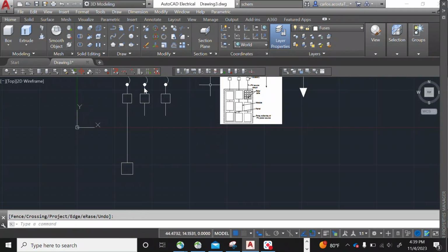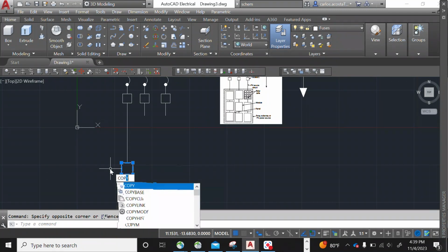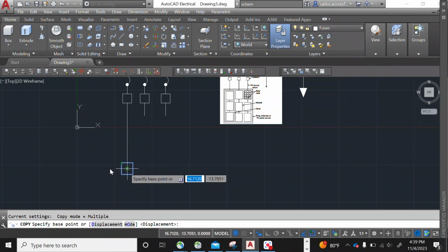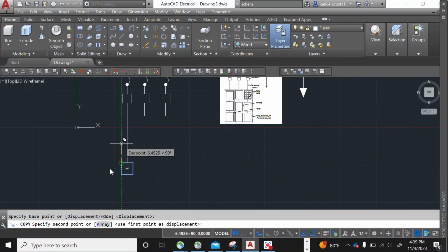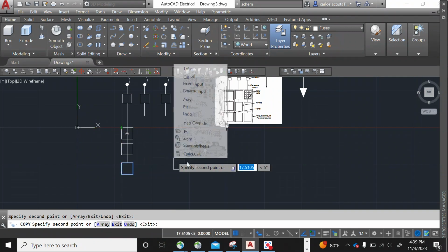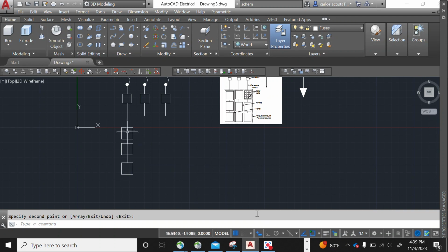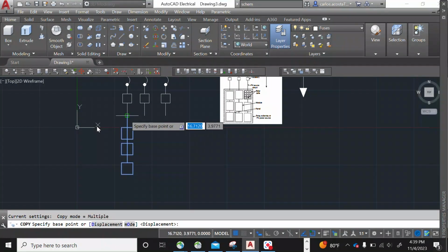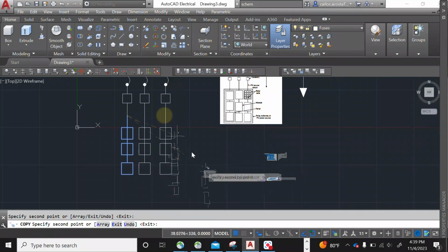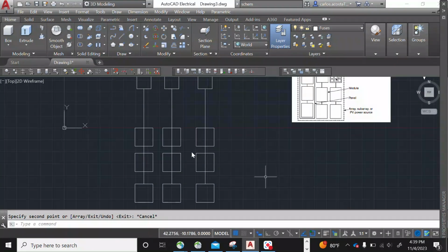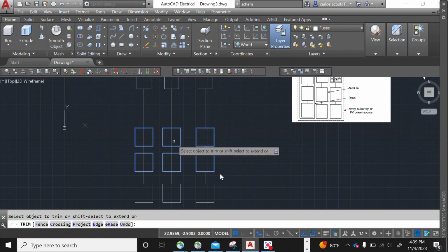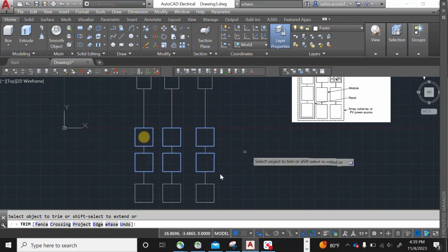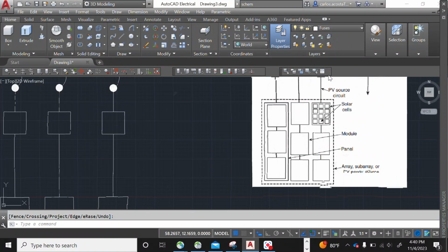Perfect. Okay, so now we can go and copy this and select the line along the same ortho line. So now they're all aligned. And what we can do is that we can copy this everywhere. And I'm still on the same layer, but I could use different layers if I wanted to change the thickness. Okay, so let's go ahead and do trim. And we're going to trim that line, this line, that line with this line. And we have the internal portion of it.